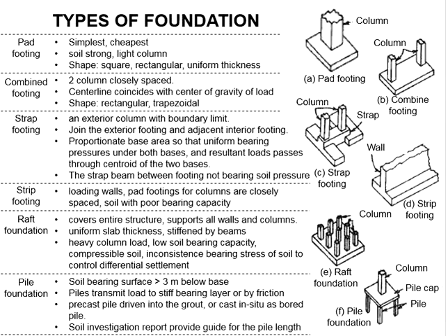On the other hand, pile foundations are normally used due to poor soil bearing pressure, where it would be unrealistic to have the pad footing acting onto the soil. Either the contact surface area of the pad footing would become unrealistically large, or the footing would clash into each other with the adjacent members.